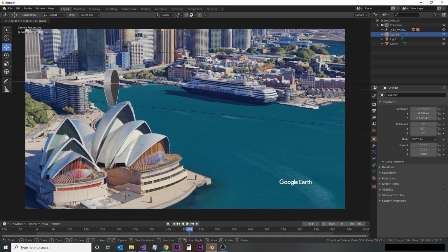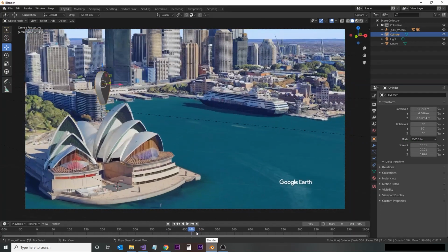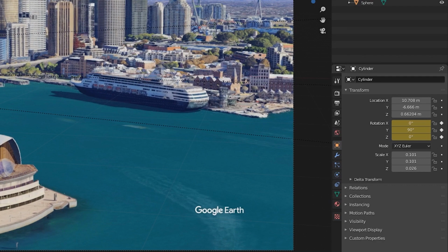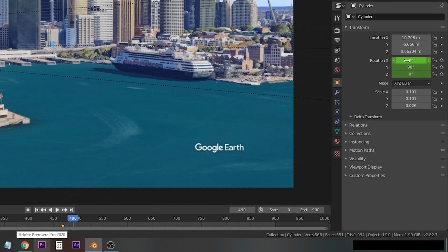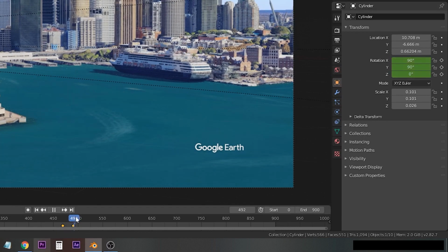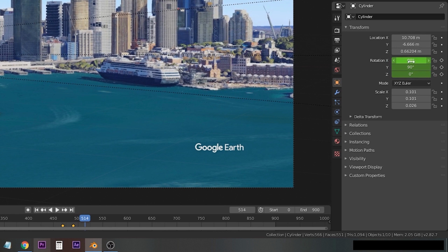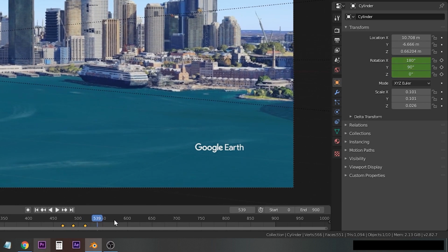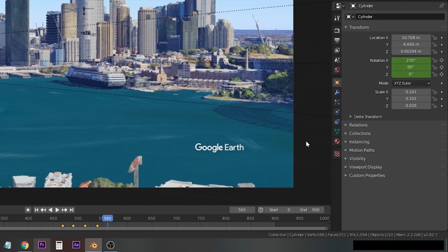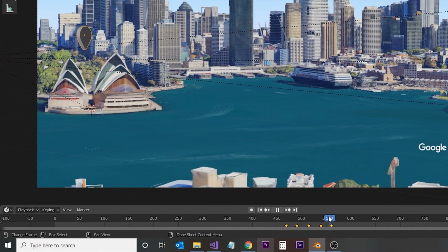And we'll just go to any frame in there where we can see the actual animation. Then mouse overing the rotation area and pressing I on the keyboard will set our first keyframe. We'll then advance the track head a few frames and change the X rotation to 90 degrees, pressing I again, advance again, setting the X rotation to 180, press I, and then advance again, setting the rotation X to 270, pressing I again for another keyframe, and then the final keyframe for a full rotation, 360 degrees, pressing I. We'll then want this to cycle itself.